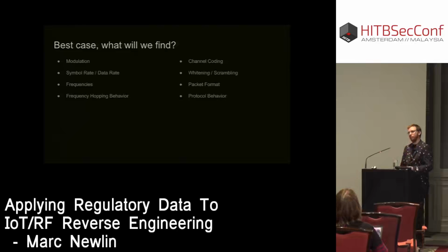So if everything goes perfectly, we really can learn all the information we need to know about how this device operates. That might be all the physical layer properties, and it also might be the packet formats and protocol behavior, depending on the device. But at the bare minimum, we're hoping to find at least what frequencies it operates on, what modulation it uses, and what channel widths it uses, so we can turn those radio waves into bytes.